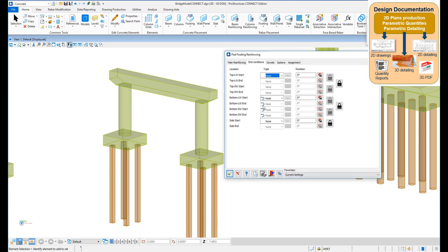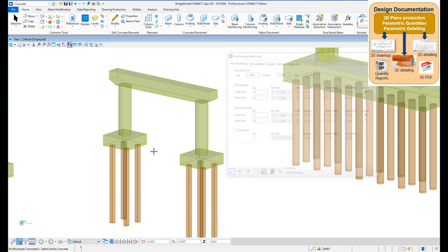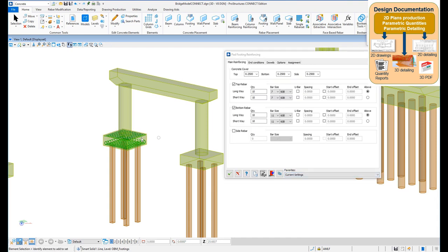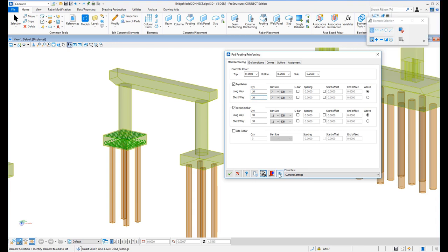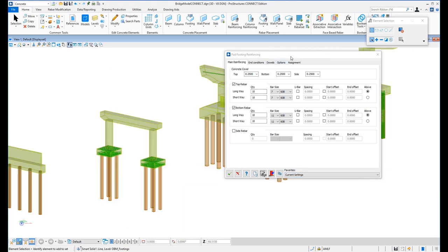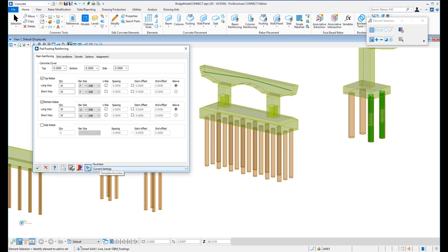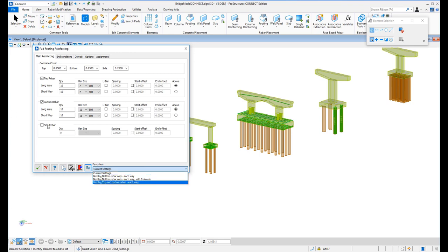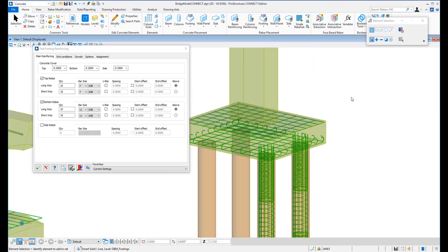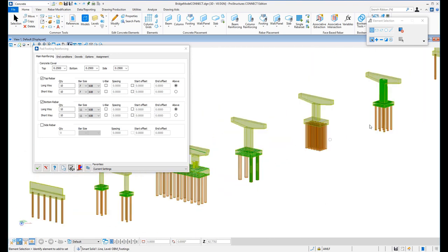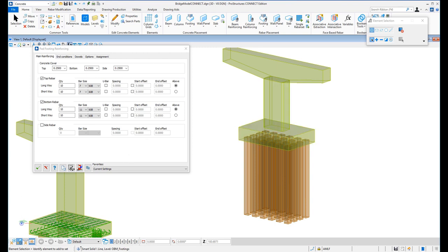Now we need rebar detailing, rebar in 3D. By the use of ProConcrete, we identify that this is a pier, this is a column, this is a footing, and annotate it all in 3D. And not just one footing, I can copy the design to all the other ones, create templates and annotate fairly quickly, model fairly quickly, all the rebars in 3D. Accurate detailing, considering the bar bending radiuses and the splice length that I need to apply to all the elements of my bridge.